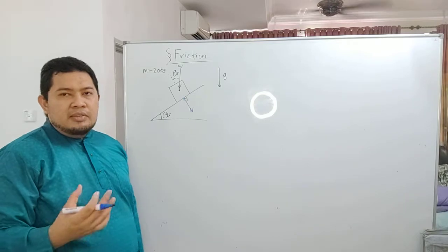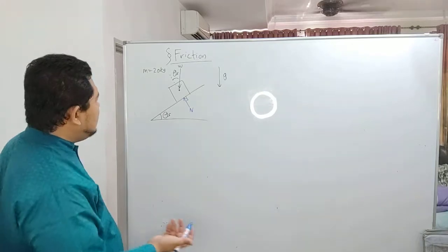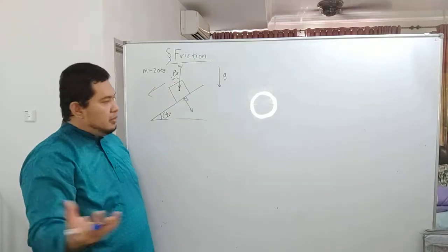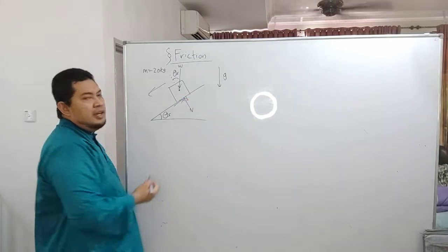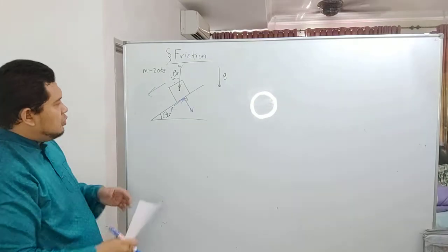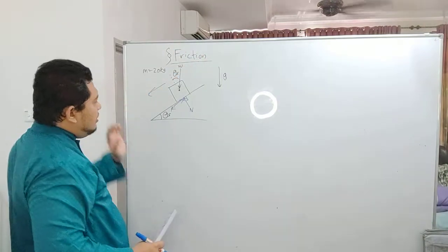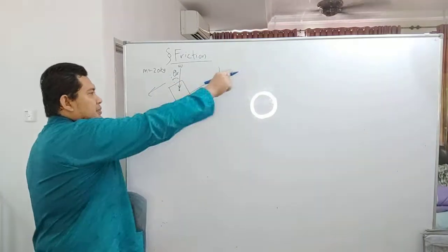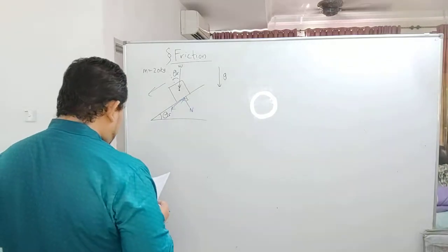Now, if you understand the friction, the direction of the impending motion, for example, over here should be moving downwards like this. That is common logic. So the friction needs to be in the opposite direction, F over here. That is the friction force that should be applied, because the intended motion is downwards, and the friction force resisting this motion should be going upwards. So of course you need to calculate this one.